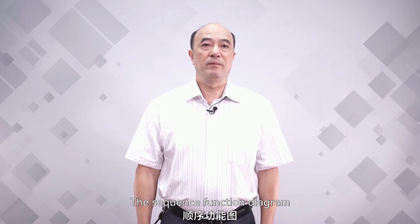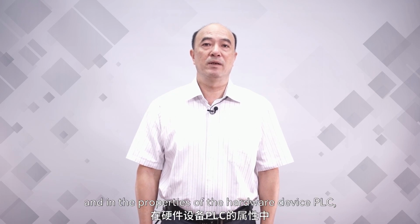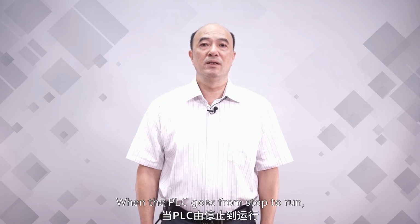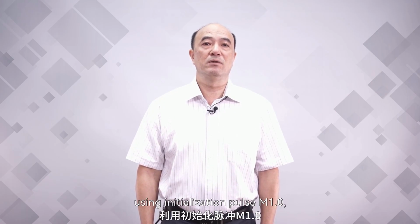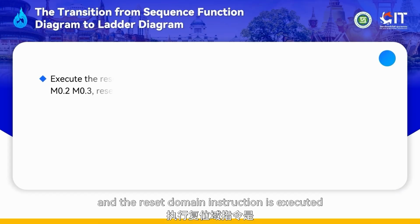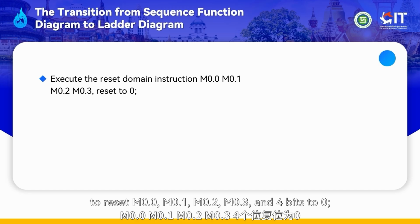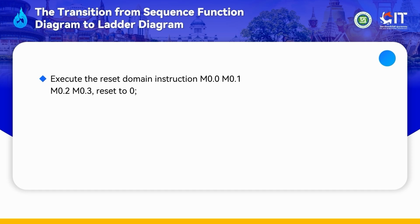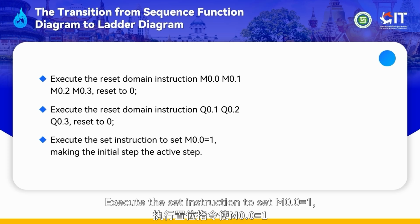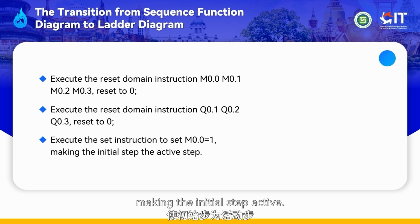The sequence function diagram is converted into a ladder diagram, and in the properties of the hardware device PLC, start the system memory. When the PLC goes from stop to run, using initialization pulse M1.0, a scanning cycle is turned on, and the reset domain instruction is executed to reset M0.0, M0.1, M0.2, M0.3, 4 bits to 0. The reset domain instruction is also executed to reset Q0.1, Q0.2, Q0.3, 3 bits to 0. Execute the set instruction to set M0.0 equals 1, making the initial step active.